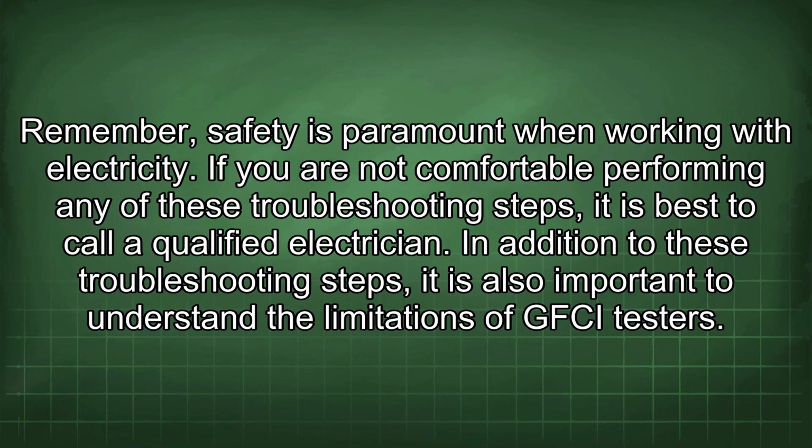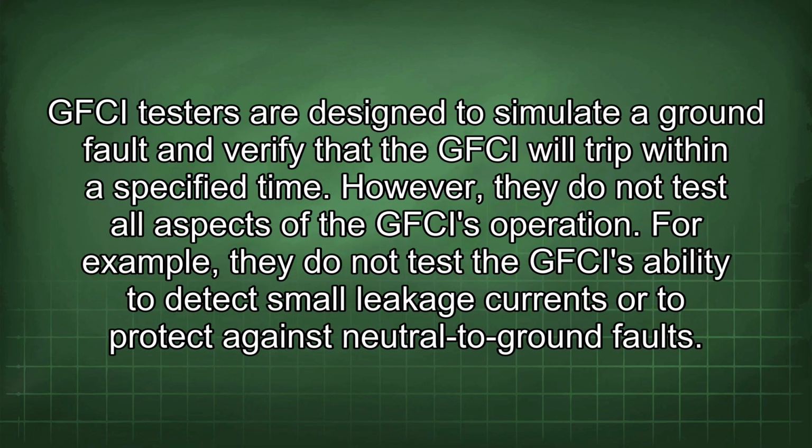In addition to these troubleshooting steps, it is also important to understand the limitations of GFCI testers. GFCI testers are designed to simulate a ground fault and verify that the GFCI will trip within a specified time. However, they do not test all aspects of the GFCI's operation.